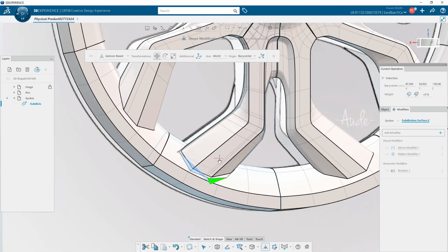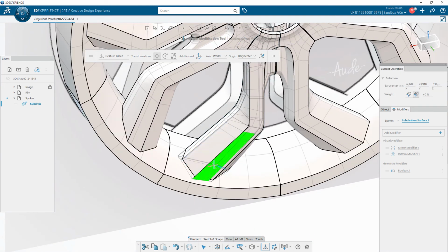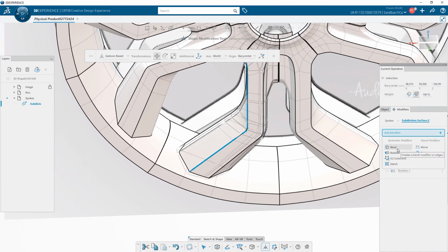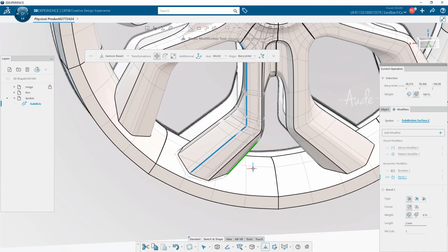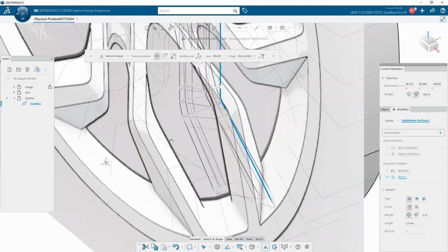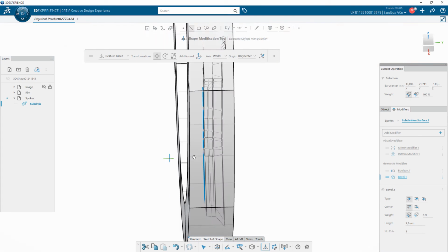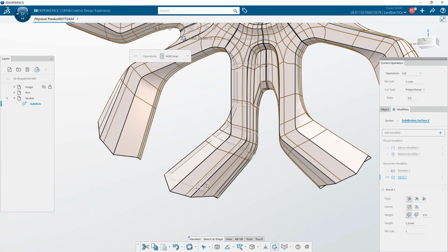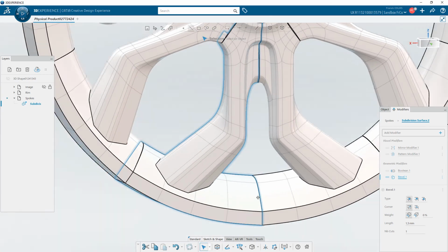I could also have simply deleted all non-necessary faces and the bevel would have been updated. I can now rebuild my bevel. I also change the weight of edges behind the spoke and the last row in the front of the spoke, just to have a totally smooth result.